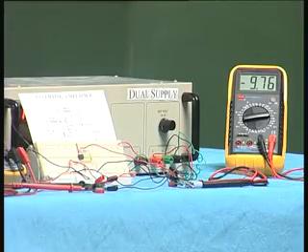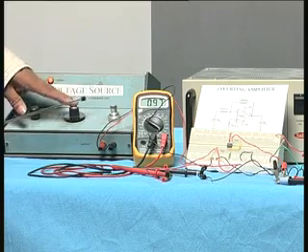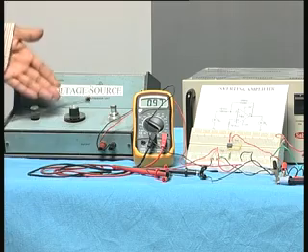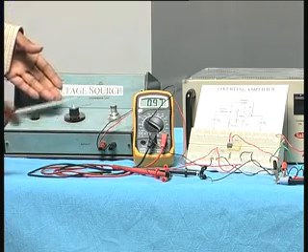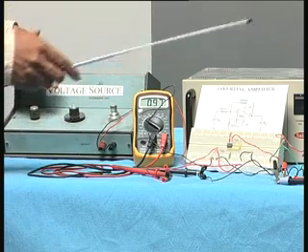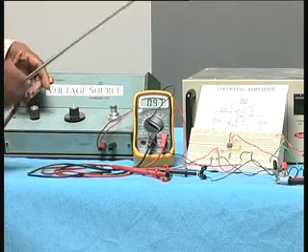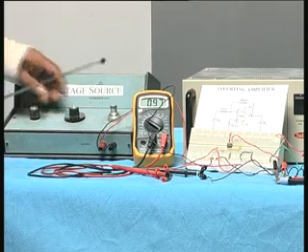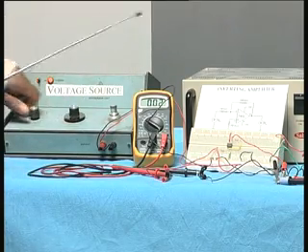Therefore I cannot increase the voltage at the input larger than 1.2 volts, because when I multiply 1.2 volts by 10 I get 12 volts, and 12 volts is the maximum that I get from the power supply. Therefore I cannot get any output voltage larger than the power supply voltage. So that is the idea I wanted to explain to you.